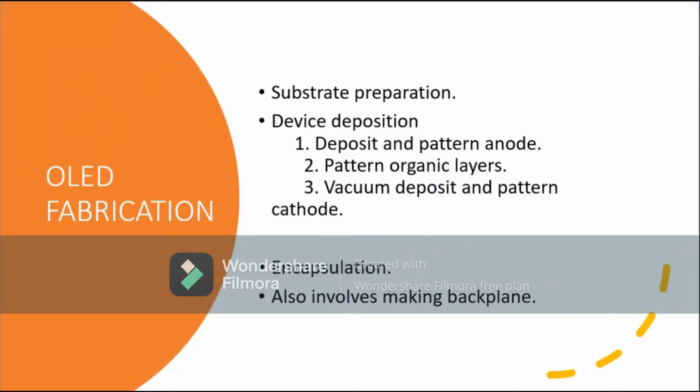Then we'll see how OLED fabrication is done. In general, the OLEDs are fabricated by either a dry process or a wet process. The commonly used dry process is vacuum evaporation. 3 types of vacuum evaporation techniques are reviewed. In wet processes, there are processes for coating without fine patterning and processes for making fine patterns. In addition to deposition techniques of each organic layer, RGB patterning technologies are important. These RGB patterning technologies are vacuum deposition using fine metal masks, wet processes such as inkjet, nozzle printing, relief printing, etc., and laser patterning process.